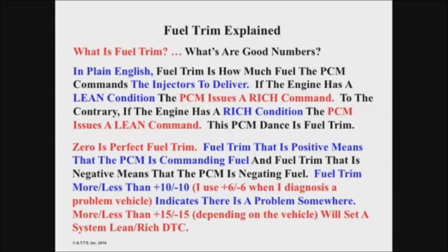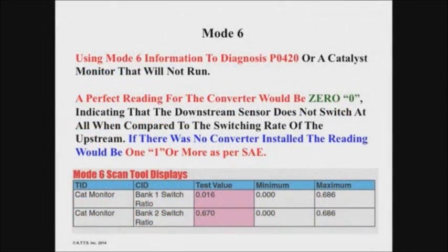Mode 6. To understand Mode 6, I'm going to give you a crash course, very simple. You all know what a DTC is. Too late at that point, you already have a diagnostic trouble code, because it's really a problem. What comes before a DTC? A pending DTC, right? Now, most state emission programs don't fail you for that. It matters, gentlemen, because why? If it matures enough, it's going to go into a full-blown DTC. And it may prevent monitors from running.